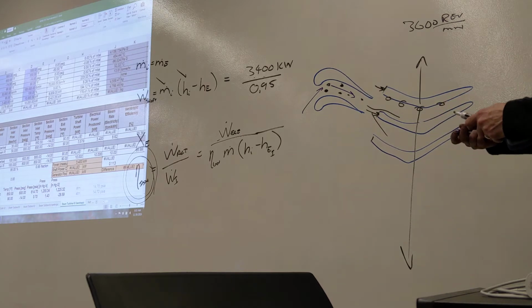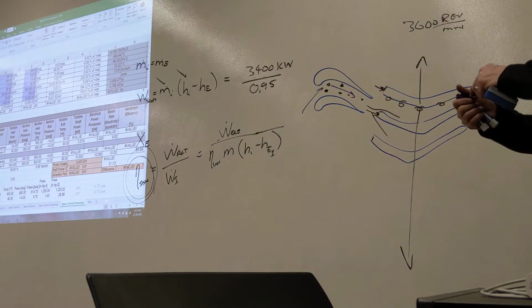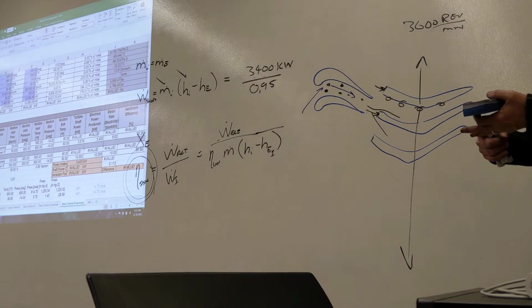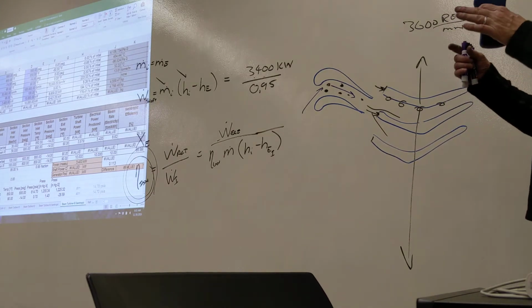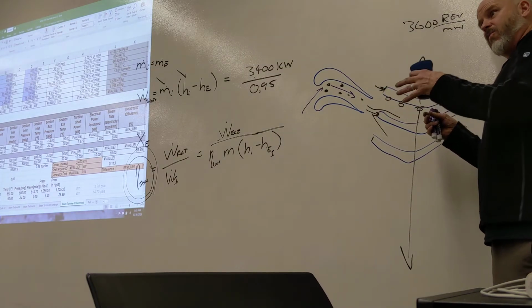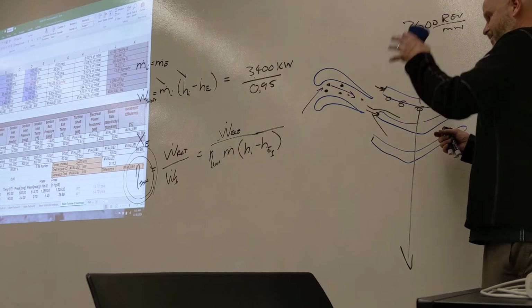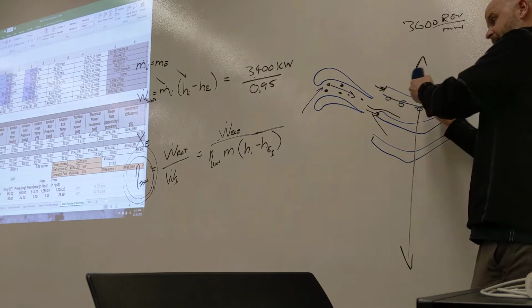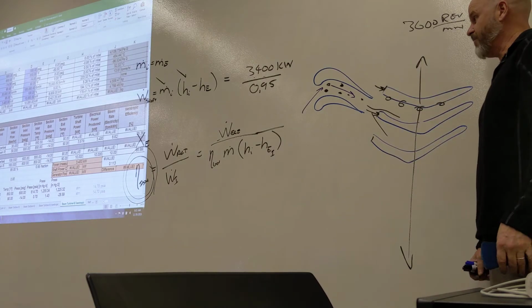So, quality, important issue, important part of the puzzle. Yes, Nathaniel? So it's like gas turbines, they have to design the blades more for temperature, since it gets super, super hot. With this one, are they designing more to be able to take more force on it, just stronger? Absolutely. More force, more strength, more forgiveness in expansion. We want to make sure that we allow these turbines to move around a little, dance around thermally and mechanically, right? So we're going to be more forgiving there.